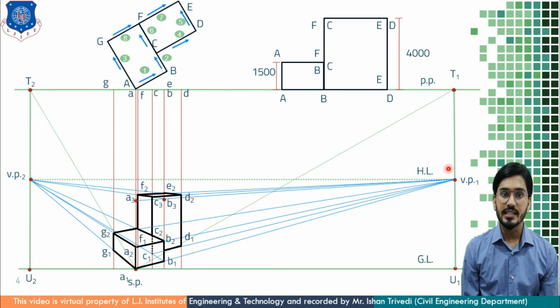I have drawn this G2F line. I am moving towards the right hand side, so I have connected this from SP, means G point, to the VP1 point, which passes through the F line, and I have just darkened the shape and completed the shape.